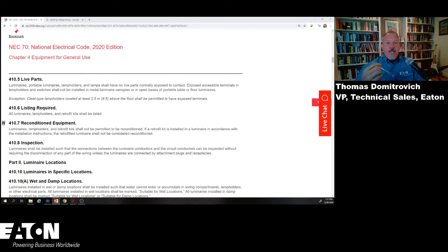In 110.19, lighting and power from railway conductors, circuits for lighting and power shall not be connected to any system that contains trolley wires with a ground return. Again, circuit connections. So there are specific requirements in Part 2, 110, about electrical equipment. Illumination shall be provided for all workspaces about service equipment, switchboards, switchgear, panelboards, and shall not be controlled by automatic means. Additional lighting outlets shall not be required where the workspace is illuminated.